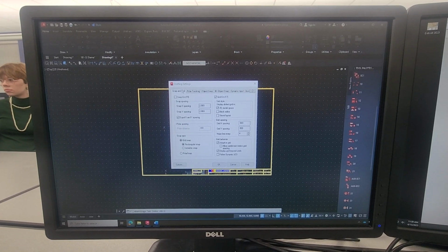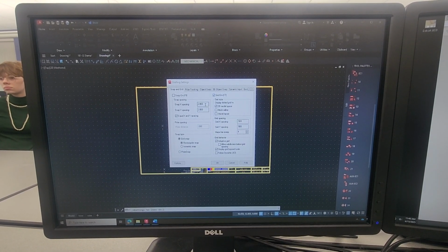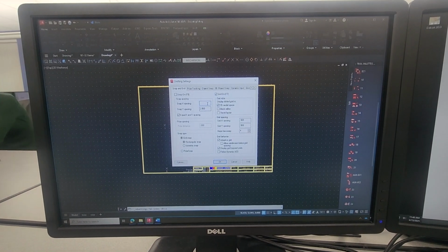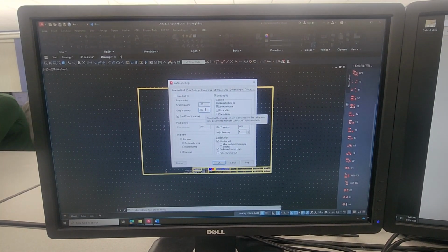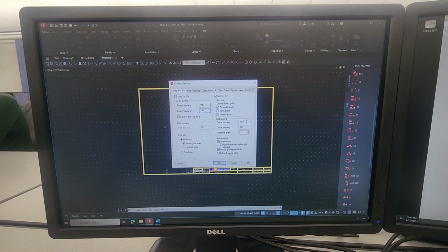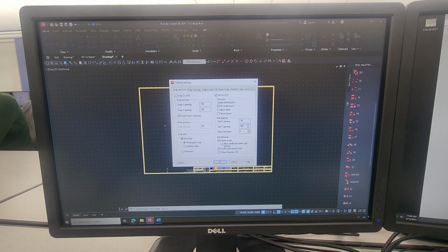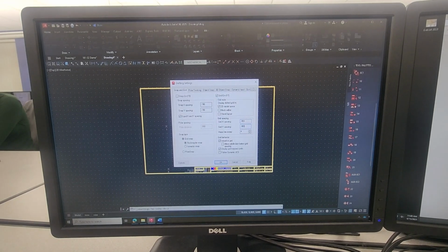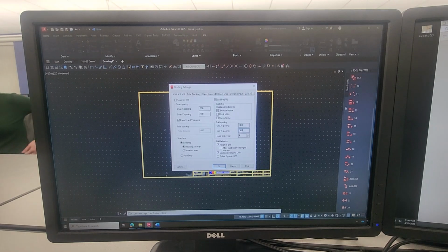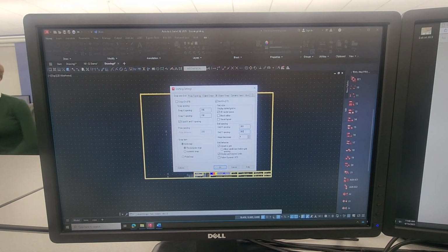Okay. So back here under snap and grid, you want to make sure the grid's turned on and set the snap right here to a value we set of 0.19. We'll do the same thing down there, and we click on that, it automatically changes. Then we'll change the grid spacing on here to be a value of 0.38. And when I click the Y, it automatically changes as well. Now, that's easy enough. You know how to do that, and you can follow those directions very clearly. There, and there's what we need. And make sure the grid is turned on, right there. That click right there, or the F7 key.